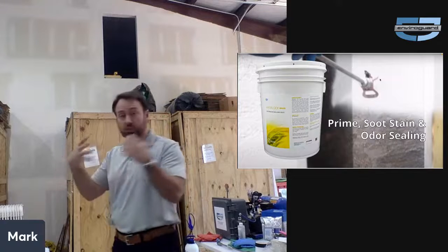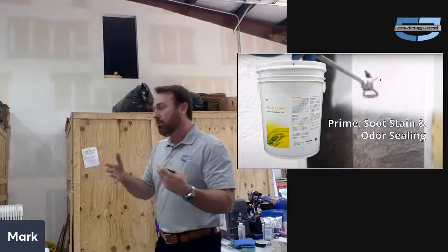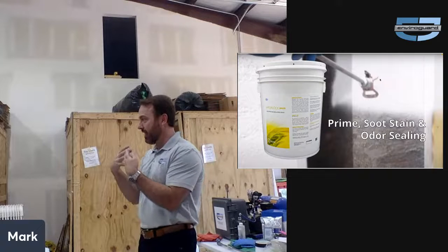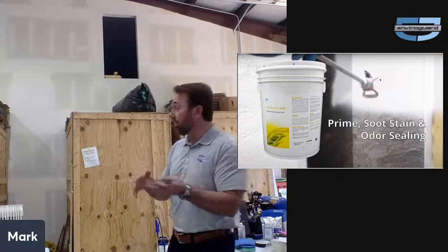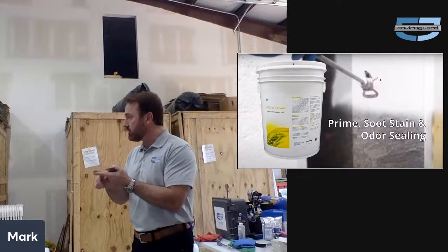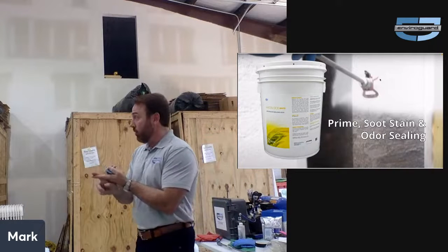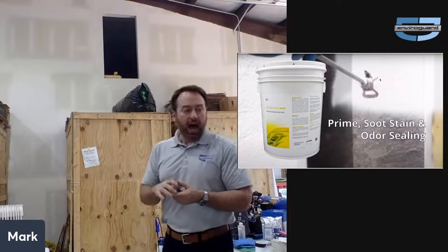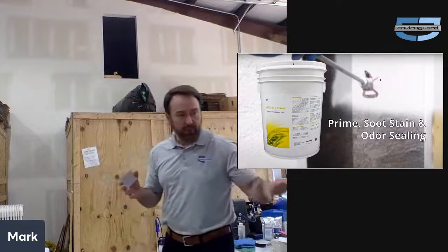So even though you might do the soot cleanup and odor mitigation, let's say with chlorine dioxide, so it smells good right now, boy, those surfaces begin to open up in summertime and things like that, then that smoke odor comes back, okay? And so Vapor Lock is the water-based alternative to a shellac product, like a Zinsser BIN or something of that nature. What it gives you is a non-VOC product. In other words, there's no gases or vapors coming off of the product. It's water cleanup only, right? So you don't have to worry about solvents to clean up your airless sprayers and those sorts of things. Yeah, it's just an easy product to work with overall. So that is Vapor Lock White.